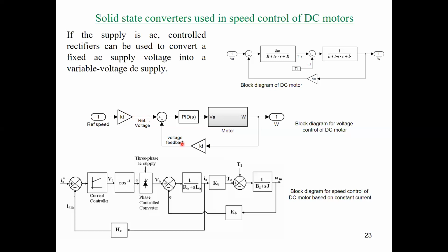Comparing the reference voltage with the voltage feedback, or the measured voltage, the result will be the voltage error. The PID controller now will work in order to reduce this error to zero, which means the voltage feedback due to the actual machine speed will be the same as the reference voltage, which corresponds to the required speed. And this is the target of the controller.